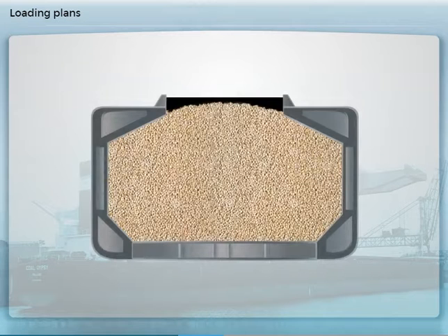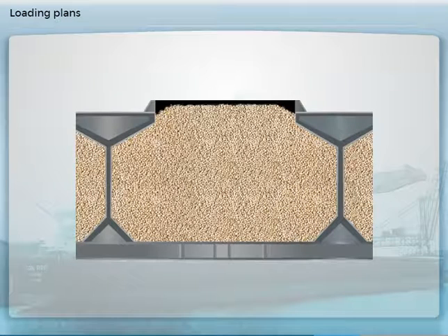Loading spouts at most loading ports cannot completely fill the ends of the holds. This causes a reduction in the ship's stability, because the grain can move in those areas. Modern bulk carriers are defined as being specially suitable, and therefore have a dispensation not to have to trim cargo ends. Some bulk carriers have stools at the foot of the transverse bulkheads, which avoid this untrimmed ends problem.